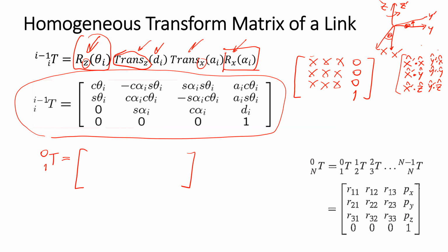You need to obtain the dot product of this, and then you can compose the rotational matrix. But of course, the origin of the frame doesn't change by the pure rotation. So the components here are 0. And you have the 4x4 matrix that corresponds to this.